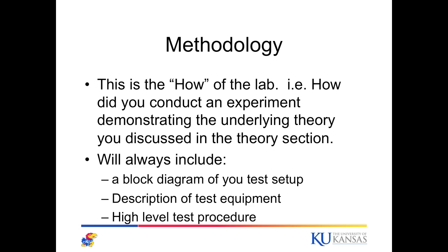We also need a description of the test equipment. This is things like, what frequencies was the spectrum analyzer set to. That way, if I built everything in the block diagram and hooked up the test equipment, I could set my equipment to be the exact same thing your equipment was set to, and then hopefully we could reproduce the exact same results. There also needs to be sort of a high-level test procedure.